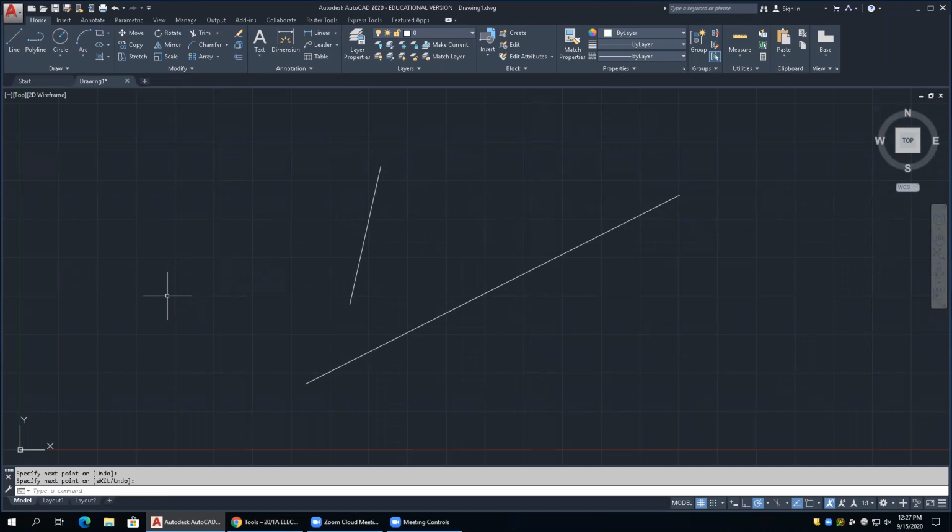And one of the objects is called your boundary edge. So if I want to take this object right here and extend him to here, I have to have a boundary edge to take him to, okay? So the first thing you select is what we call the boundary edge.